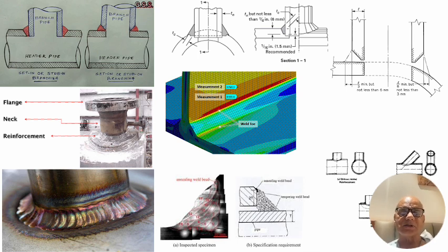Placement of fillets is very critical. The start of a fillet is also very critical. Where are you actually tacking it so that you have the best point where it gets locked? Like in our earlier slide, if you are tacking it on the sides, if it is possible to do it, most of the time it is not there.